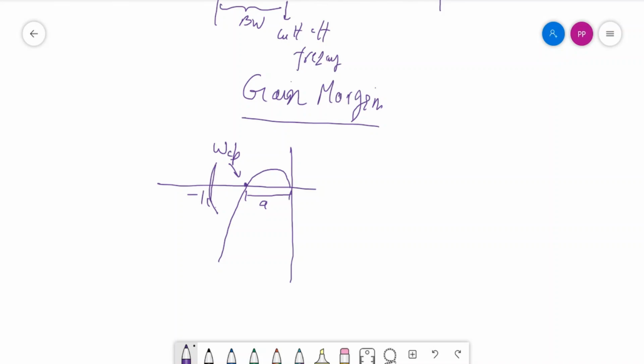So going further, if we speak about the phase margin, we should always say that phase margin is acquired at the gain crossover frequency. So this magnitude of 1, which is the radius, should be crossed in such a way that the crossing point of the gain magnitude 1 provides us with the gain crossover frequency. So this is the gain crossover.